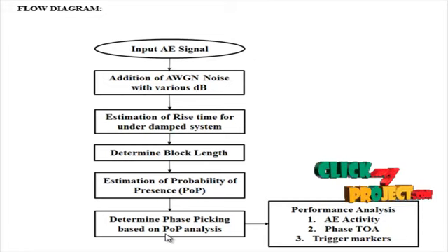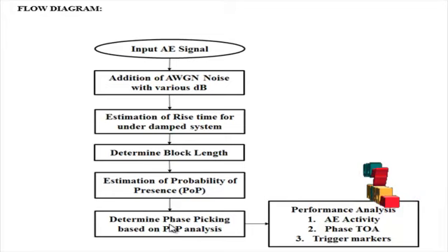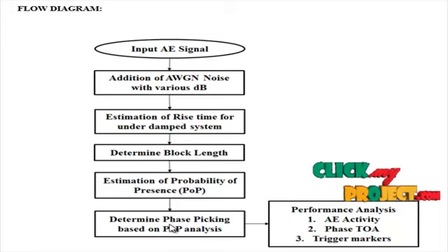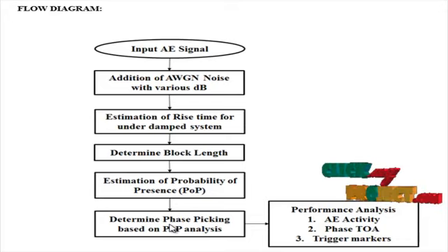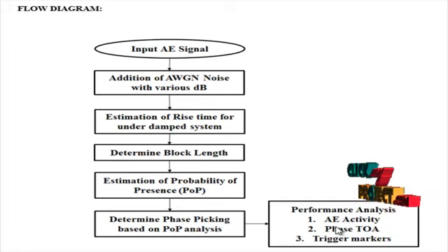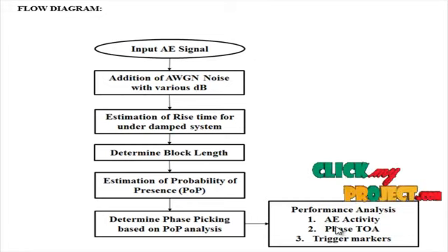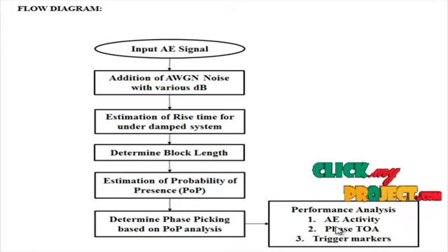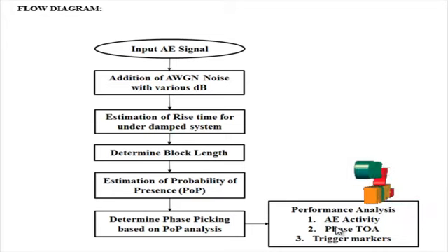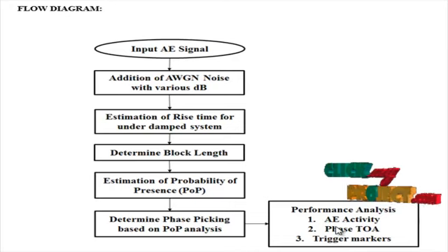Then the time of arrival. TOA estimation requires enhancing the time domain resolution of the channel response in order to resolve the paths and enhance the accuracy of estimation. Compared to the TDOA technique, time of arrival uses the absolute time of arrival at a certain base station rather than the measured time difference between departing from one and arriving at the other station. The distance can be directly calculated from the time of arrival as signals travel with a known velocity. Time of arrival data from two base stations will narrow the positions to a position circle.